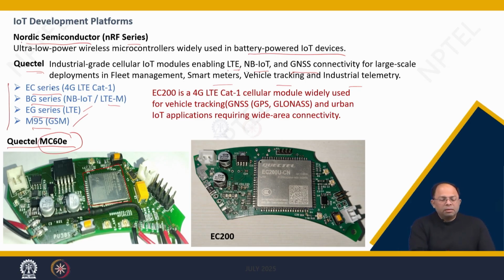Now in this case the PCB or the peripherals are designed by us only. That means here we have not used a board. We have bought the microcontroller, we have designed the circuit, like this microcontroller needs to be connected with an accelerometer, it needs to be connected with a speaker, it needs to be able to be charged by a battery. All these things are done, right? So that means instead of a ready-made board, we are making our own PCB or printed circuit board, and we are putting all the components within it to do whatever we want. So this is a custom board with a microcontroller which is available from the market, and each microcontroller has certain capabilities. Accordingly we choose them.